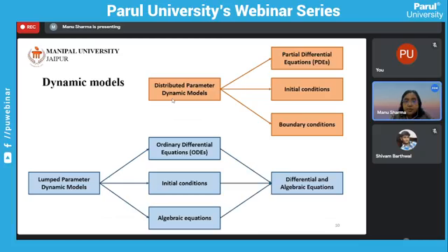However, if the mixing is improper, then different zones will be formed inside that reactor. Temperature zones, hot zones will be formed. The concentration at different points will be different. That means the concentration is changing with time because the reaction is happening over there. As the reaction proceeds with time, more and more product will be formed. So concentration will change with time. At the same time, the concentration is also different at different places. So it is also changing with space.